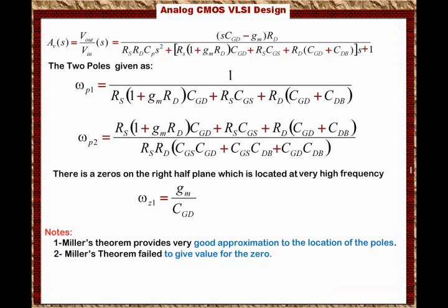amplifiers. In ultra-wideband amplifiers, we are interested in very, very high frequencies. So in ultra-wideband amplifiers and low-power amplifiers, what that means is GM is very small, and we would like to have very high bandwidth, right? So these two requirements are important. In low-power amplifiers, remember GM is a function of the bias and current, so you have to make sure that the bias and current are very small for low-power amplifiers. And we are interested in very large bandwidth.